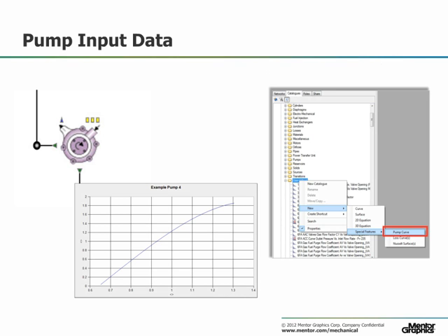The Suter parameter is a non-dimensional performance curve which converts the pump affinity laws to a form more suitable for computational analysis. The parameter can be used to describe the variation of head or torque with flow rate and rotational speed. There is a special feature option in the catalogs to allow the user to create this curve.